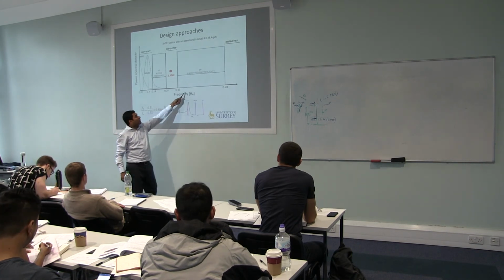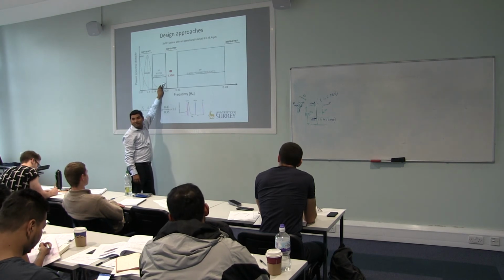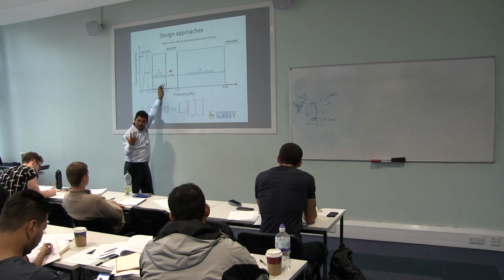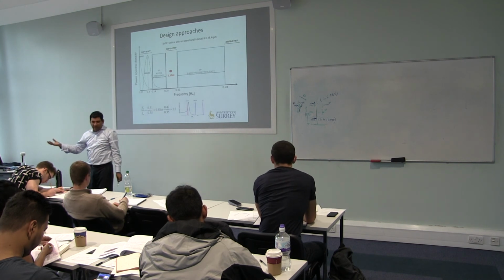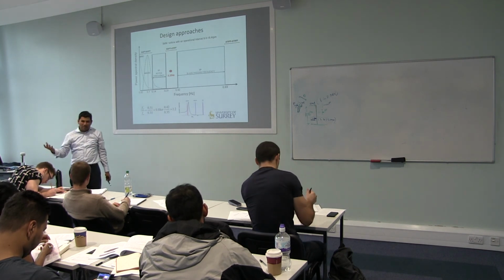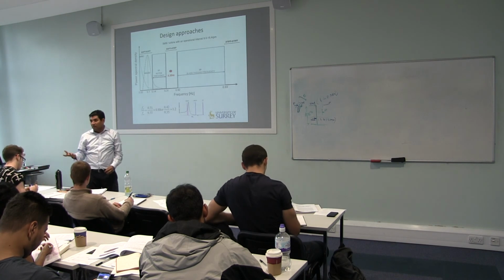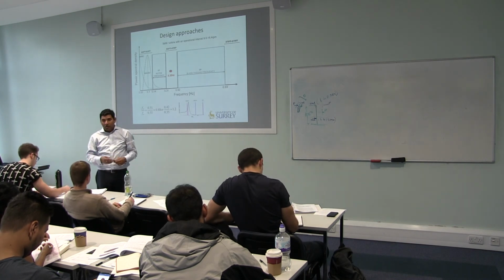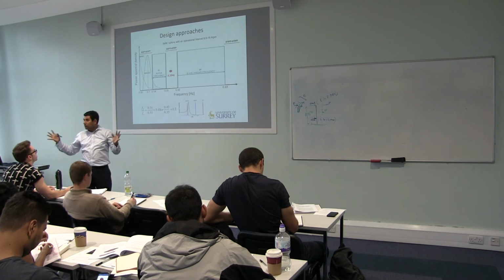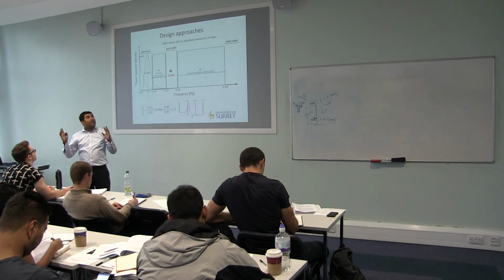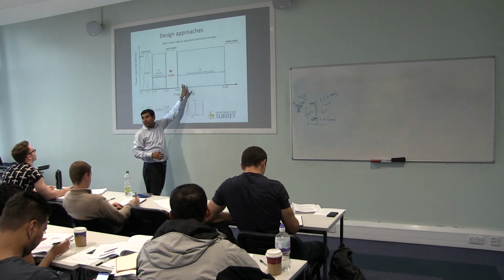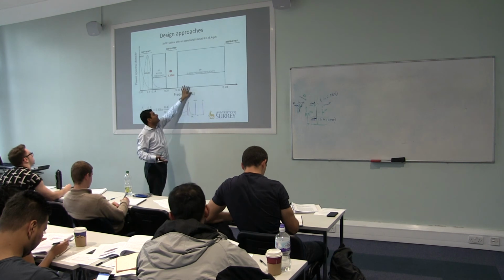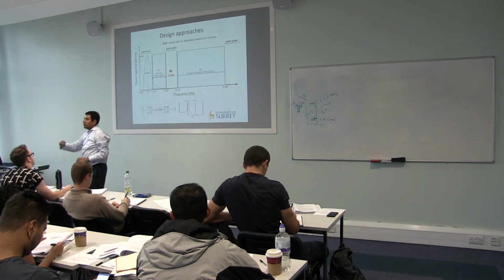Would you dare to put your turbine in this range? No, why? It will resonate. If it resonates, you will start to wear and tear your gearboxes, your blades will start to crack, you need a higher maintenance cost. In some cases it might fail, because you are trying to resonate. So you have to avoid the whole thing. That's why your target is not in these bands. If by mistake you are in this band, you have to abandon your design. Nobody will certify your design.